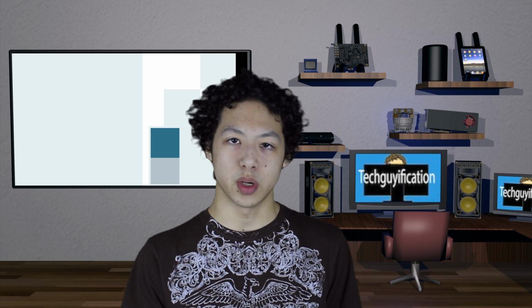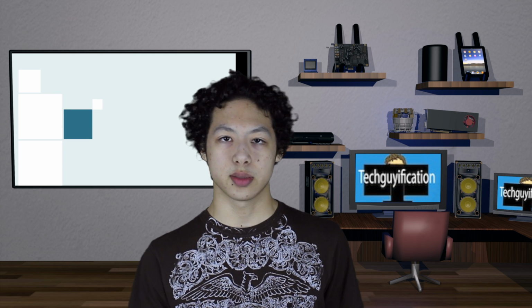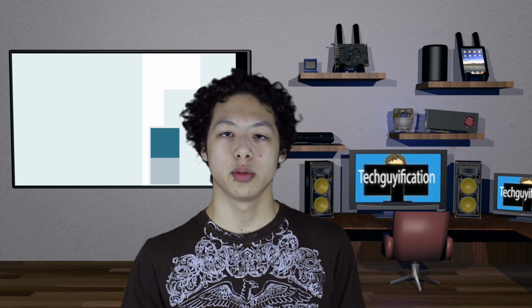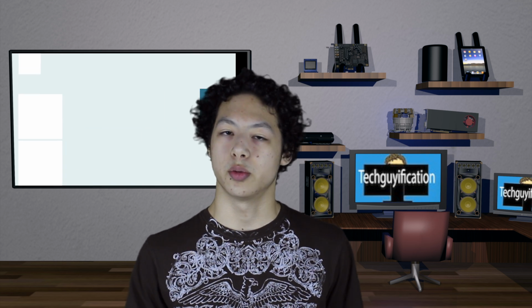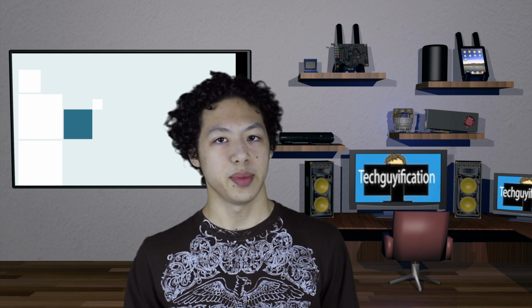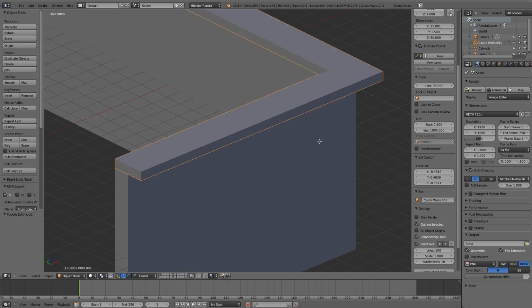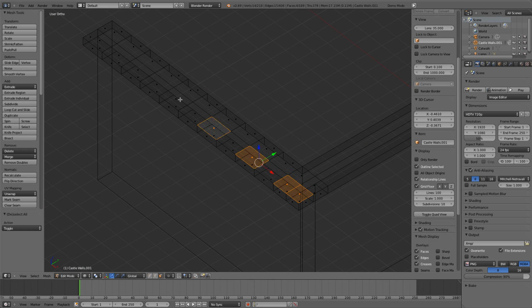So Tab out of edit mode, and if you're still in wireframe mode, press Z to switch to solid shading mode, and then you can rotate your display to see exactly what we've done. At this point, I would recommend that you save your file, Control S on Windows, Command S on a Mac. So now repeat this process for the other front catwalk on the right hand side of the castle.